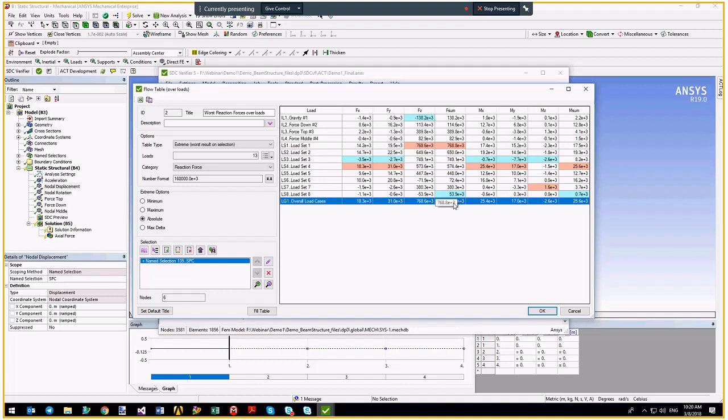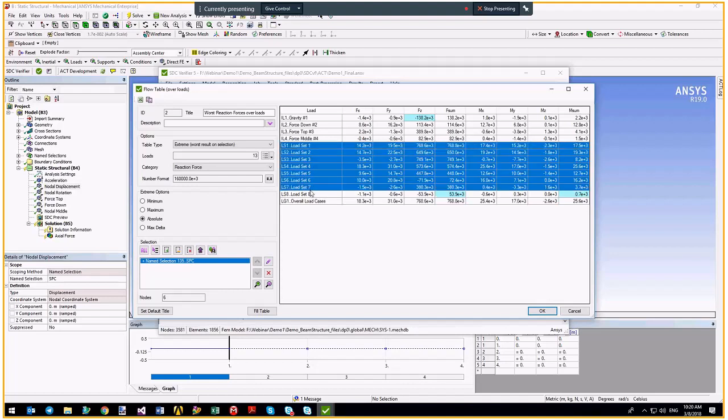So this example demonstrates the difference. Load sets, it's summation of the forces from individual loads multiplied by factors, and load group is envelope. It looks for worst result among its items. So in my case, it's all load cases.